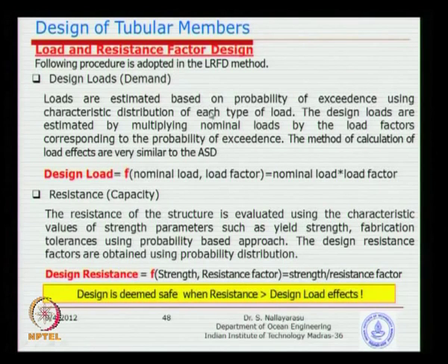For offshore platforms, there could be variabilities, but not too much, because I do not think you will transport too much of the loading to the offshore platforms every time. Environmental loads are highly variable, because the estimation itself is very uncertain. So you could see that for the design loads, the variability has to be accounted for.